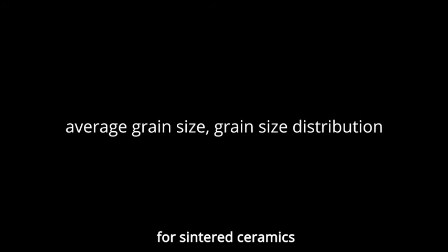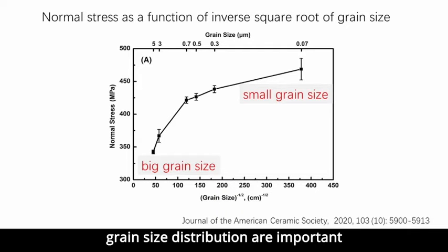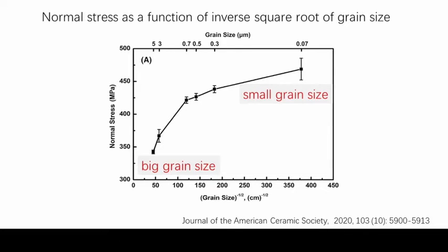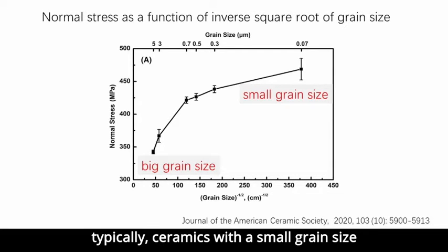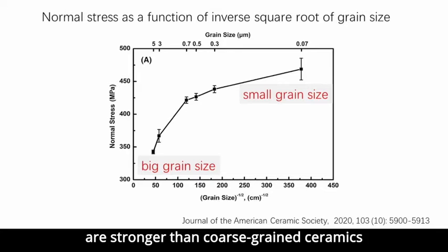For sintered ceramics, the average grain size and distribution are important. Typically, ceramics with small grain size are stronger than coarse-grained ceramics.